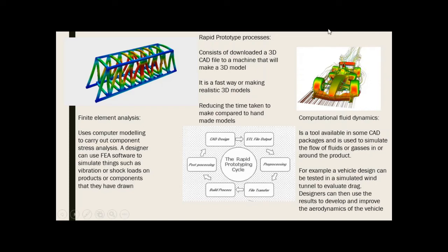And then the next one is rapid prototyping. This is where you have your CAD software, you have done your drawing, and then, typically with 3D printing, you can make rough models of your thing really quickly. So it lets you model it. We've got a 3D printer, and if we just want an idea of the overall shape and size or ergonomics, we'll do it on CAD and set it up on the 3D printer. That'll take a couple of hours to make.